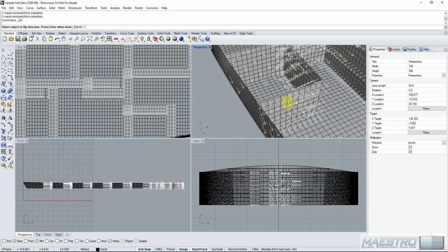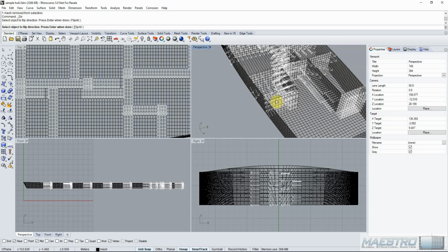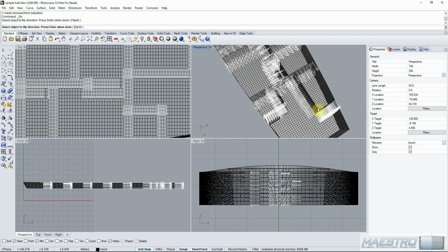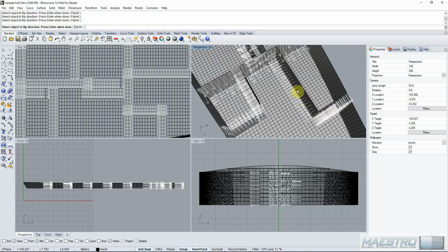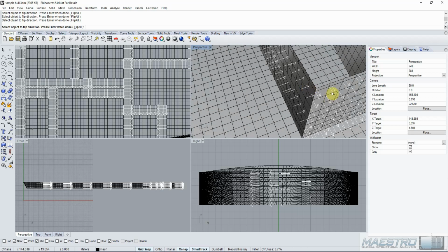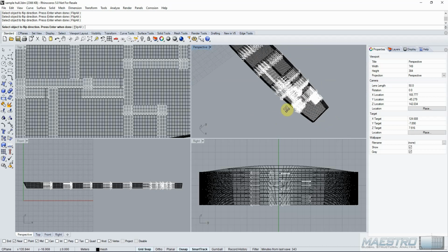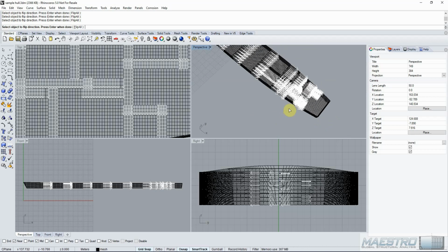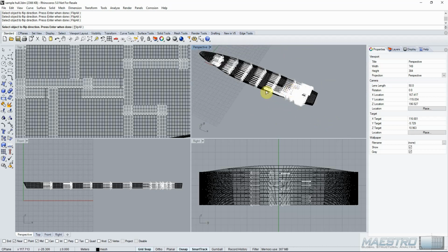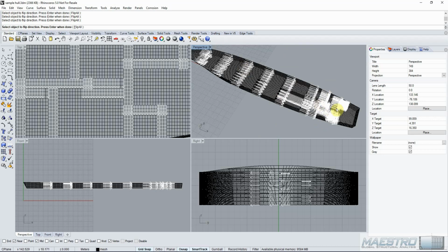So if we wanted the stiffeners on the forward side of this bulkhead, we simply flip the normal. Which can make it easy to rearrange these things. Using the normal will take a little more time in exporting the beams, but it can save a little work later on.